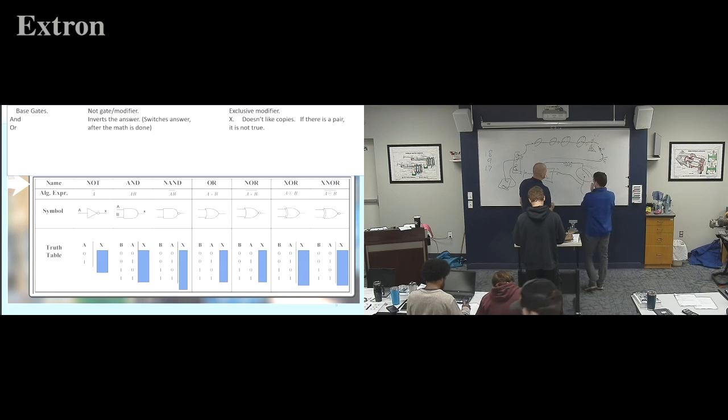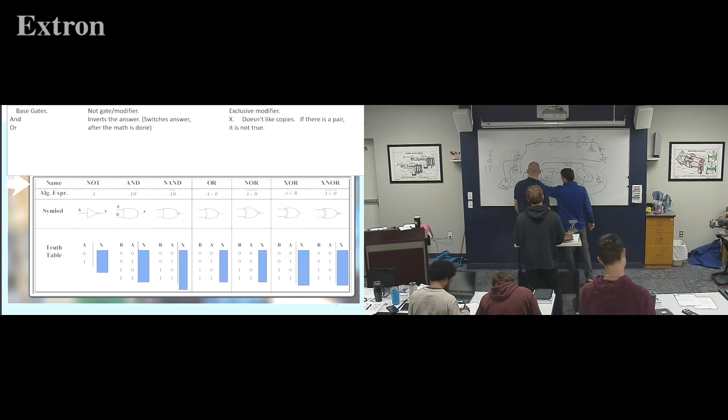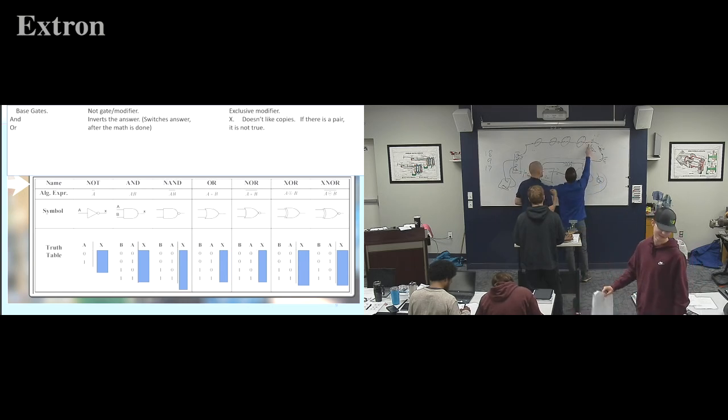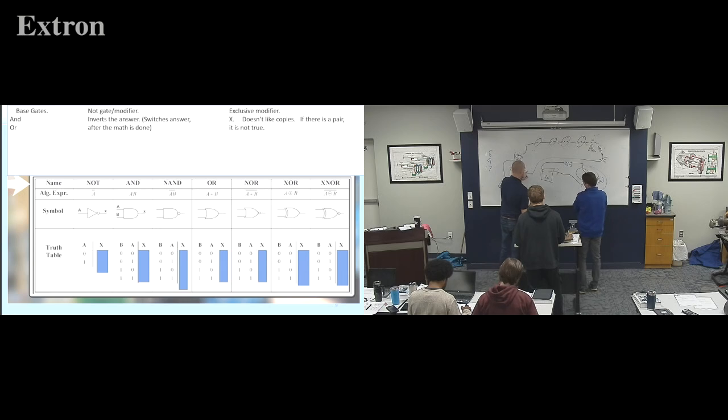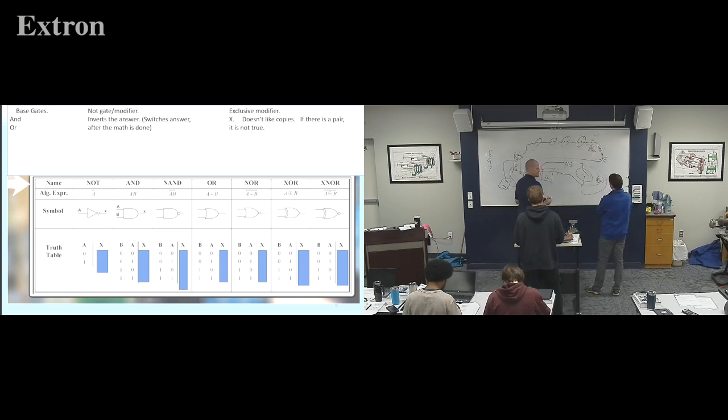No, sorry. I thought the one time we were looking at it, you put the voltmeter here. Okay, what would that be? That would be 0 volts as well. So this one's still -6, right? This one's my +6 side. So -6, +6, it's a 12 volt difference. So then, if you close it and still keep it there and there, does that automatically go to 0 volts, because it's just a wire? Yep, I close it, it goes to 0.